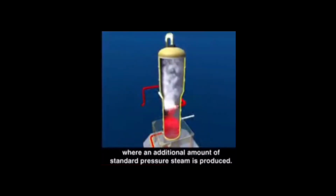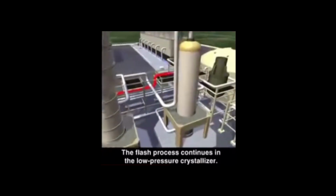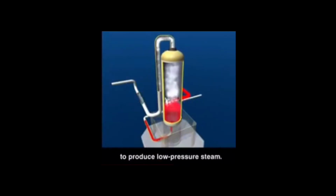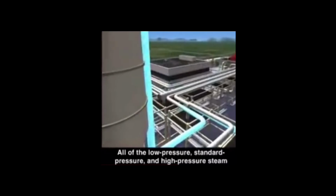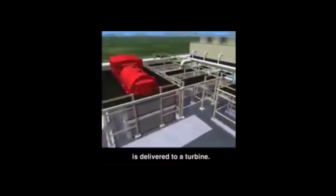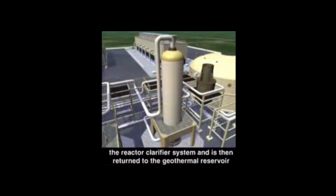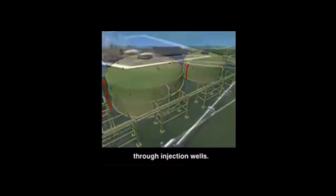standard pressure crystallizer, where an additional amount of standard pressure steam is produced. The flash process continues in the low-pressure crystallizer. The remaining fluid is again flashed, this time at a lower pressure, to produce low-pressure steam. All of the low-pressure, standard pressure, and high-pressure steam is delivered to a turbine. The fluid that is not flashed into steam flows into the reactor clarifier system and is then returned to the geothermal reservoir through injection wells.